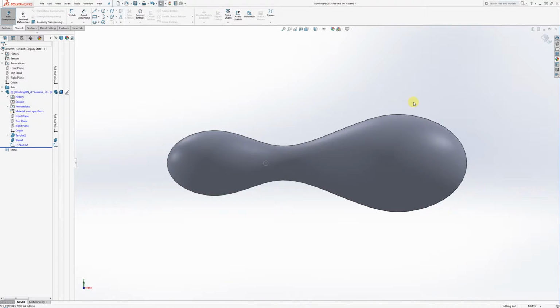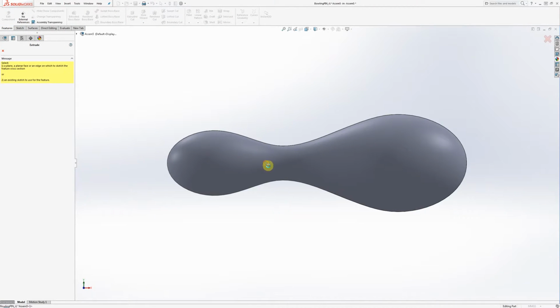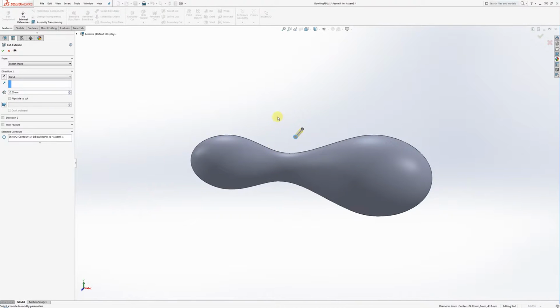Anyway. There's my circle, okay, and remember that's a key circle because that's the thing that we're going to use to set our concentric mate to our bristles later on. So we have to remember that this sketch exists, and we have to plan ahead that we're going to use it later on. For now, I can just go ahead and go to Extruded Cut and then accept this as the thing to extrude cut.